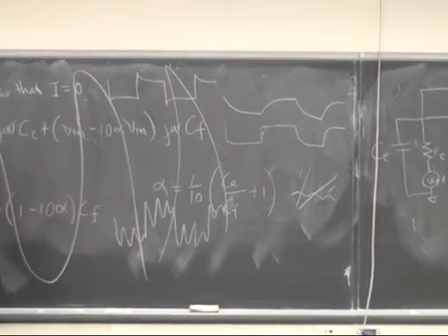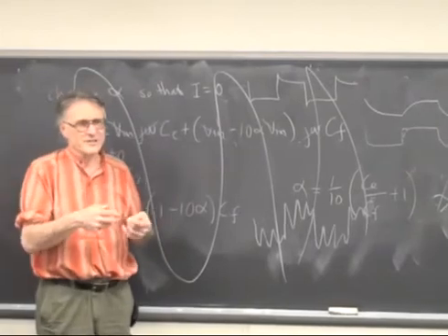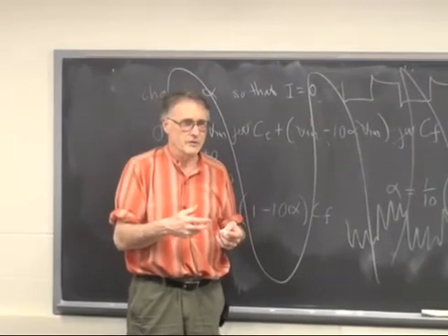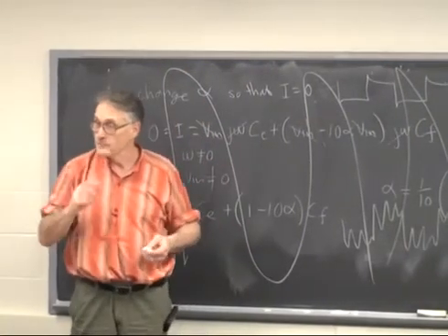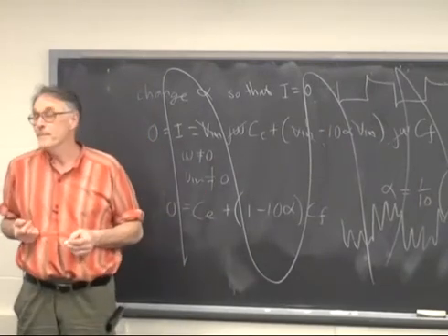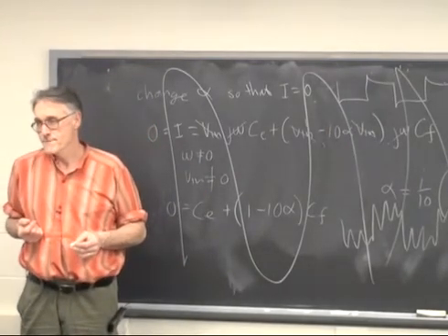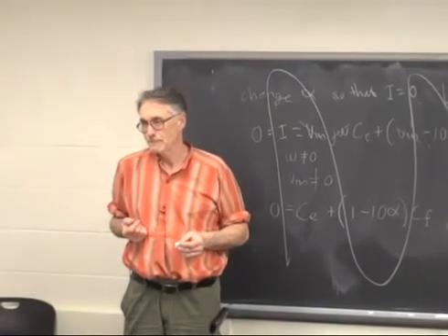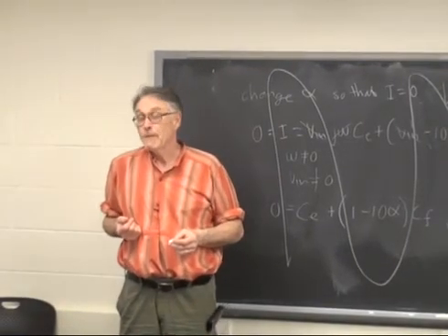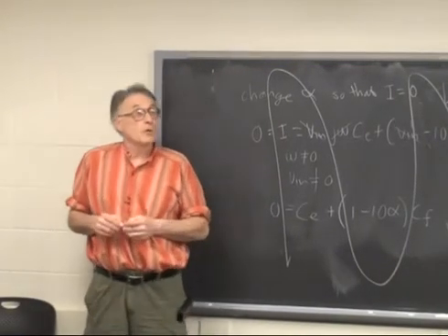There's also usually a little bit of capacitance around the terminals of the op-amp itself that are hard to shield away. Maybe I'm forgetting my basic op-amp stuff, but why can't you just put a high-pass filter in if you're trying to amplify something and there's a high frequency coming in? Or do you still have to worry about the high frequency?